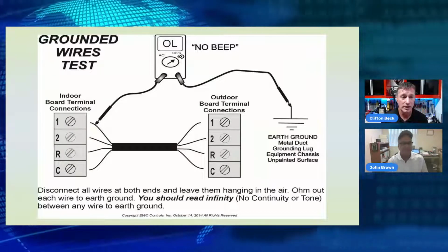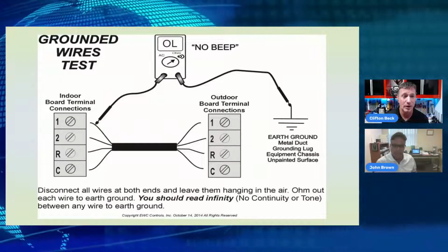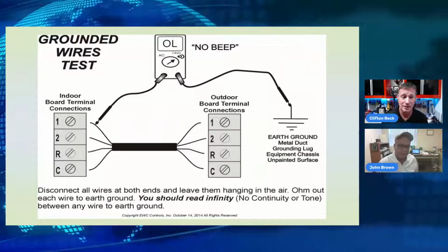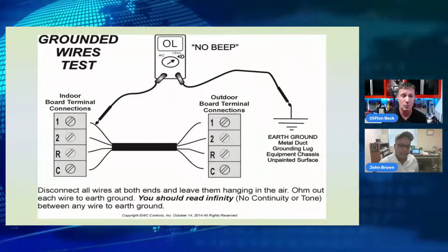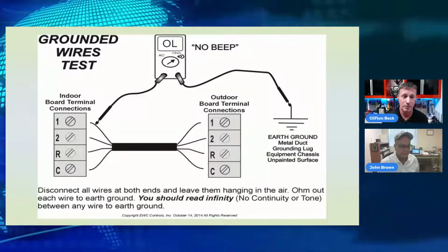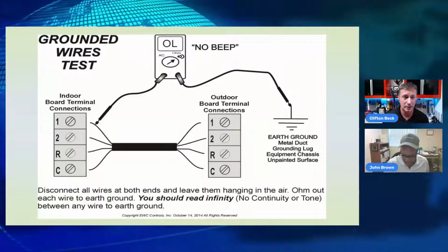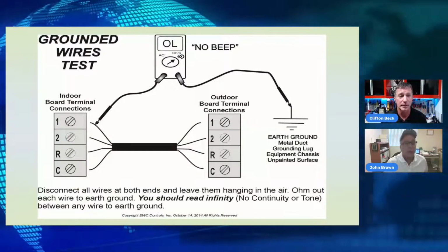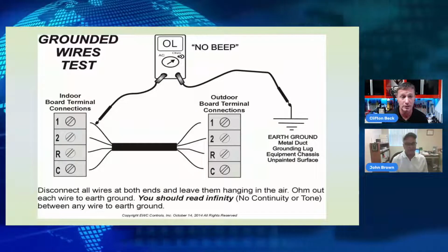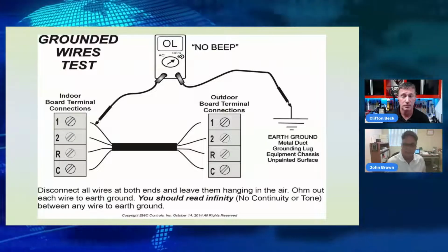Here in the Midwest, when we have a basement with a sump pump, a lot of our installations now we're using poly PEX water lines and gas lines. You got a sump pump, you grab your piece of copper wire, you strand it, and you shove it down into the water, and now you have a good, clean place to measure ground. So plenty of places we can find good ground.